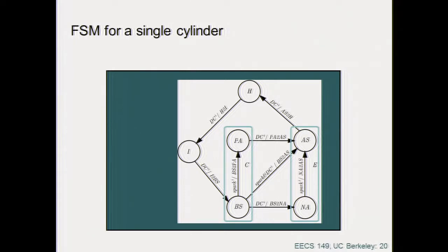So this is a process that you follow to take a complicated physical phenomenon and try to find what matters, and throw away the unnecessary details, and yet be accurate enough that you can take good decisions on the control action, which is when you give a spark. Now, you know what people did before using this finite state machine model? They used average values for everything. So instead of taking up, down, we took the average to decide what control action to take. And of course, you had knocking, you had all kinds of bad stuff.